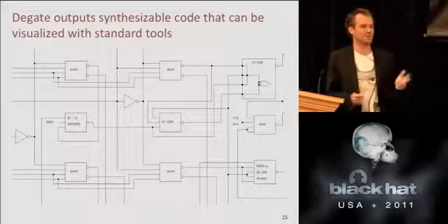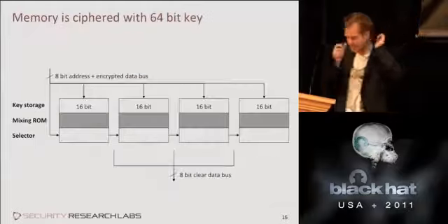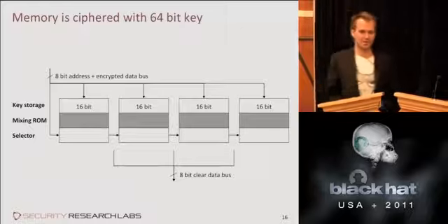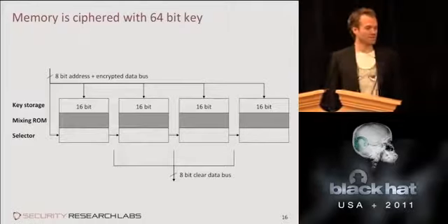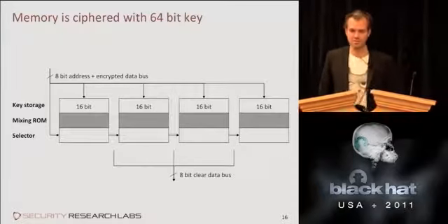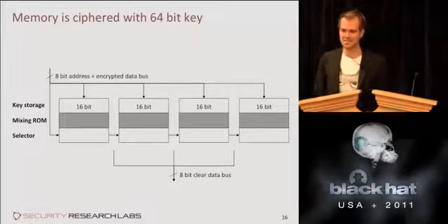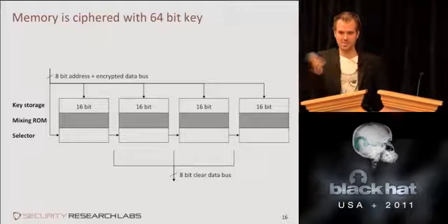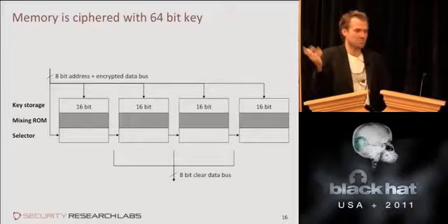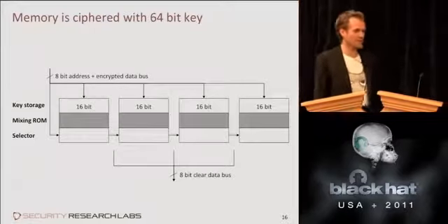There must be some IV input. There must be some cryptographic structures. And we did in this chip find a 64-bit block cipher, one that's weaker than anything we've ever seen cryptographically, but that also solves a problem, or tries to solve a challenge that nobody else really has. Since this is a kind of in-wire encryption, the chip doesn't know it's there. It wants to access the memories in one clock cycle. This has to operate in half a clock cycle, right? So a 64-bit cipher operating in half a clock cycle.